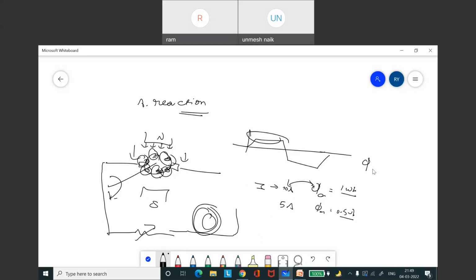Our main field flux is always, say, 2 Weber, for example. Suppose these two are opposing. The opposition is less now, as it further decreases: 0.5 opposing compared to 1 opposing 2. So the main field flux in the air gap is trapezoidal. The main field flux is maximum along the magnetic neutral. See, this axis is called the magnetic neutral. The main field flux is always maximum along this magnetic neutral axis.